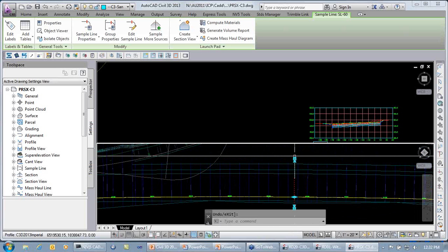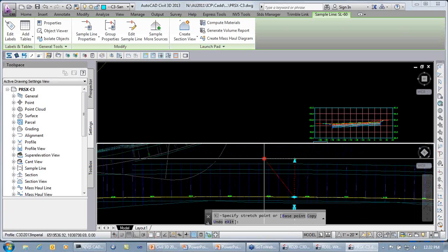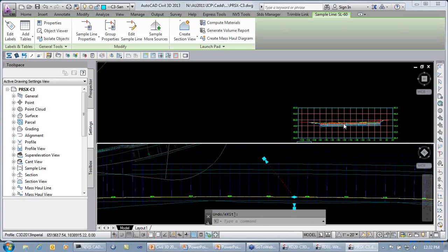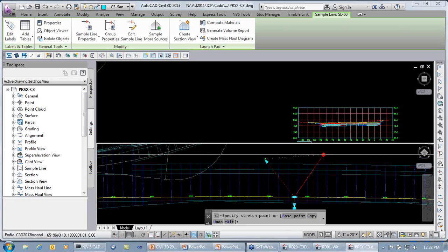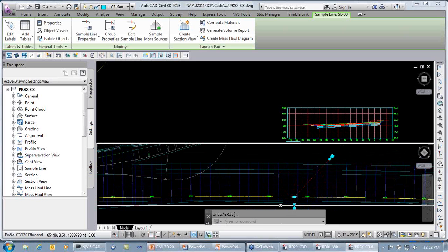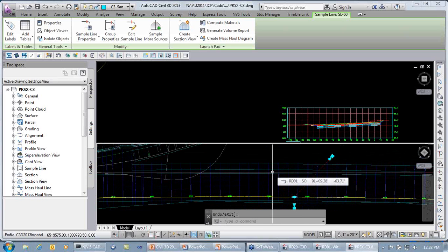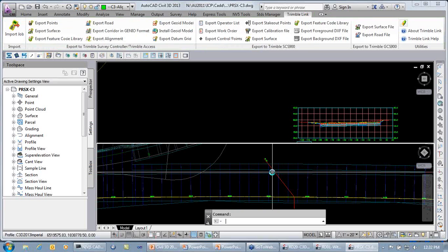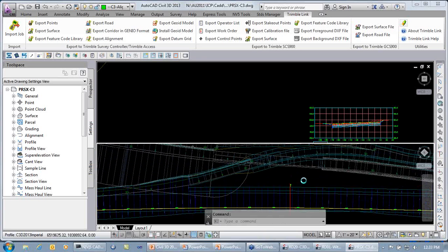Okay. I can also change the angle, and it will update and show me all of the components that I drag that through. You know, so maybe I want to do a section through some culvert going through at some odd angle. I am now able to do that. We're no longer limited, or no longer have to create a whole series of surfaces from our corridor models in order to get that data to show up in our section view.